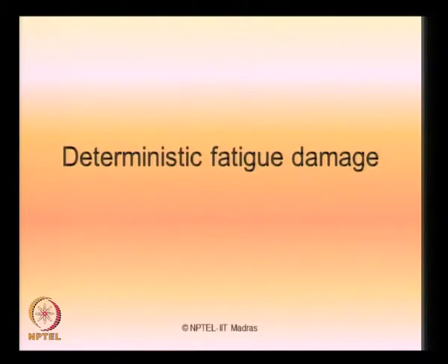In the last lecture we discussed the time history. Once I have the stress range time history available to me, I can use what we call the rainflow counting technique to find the fatigue damage of each stress group and subsequently the cumulative fatigue damage. Okay. In this lecture we will talk about deterministic fatigue damage using the spectral approach.